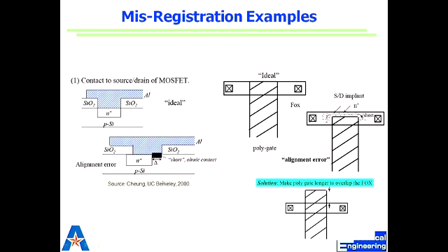The resistance will increase. I just covered half of it. My contact area has become half. And my resistance is what? Will increase. What's the formula for resistance? Resistivity multiplied by length divided by area, rho L over A. We all know that R equals rho L over A. So my area is half, which means my resistance has doubled. My resistance gets doubled, what happens?